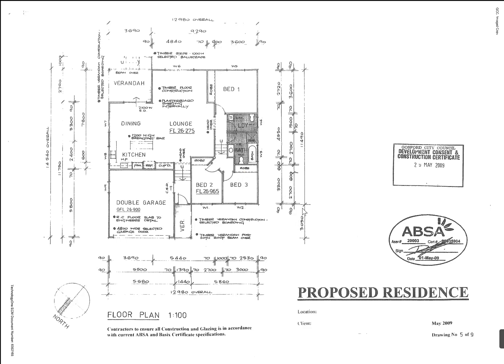Now, looking at the dimensions, basically what happens with all projects is that the furthest dimensions from the actual building give us the overall length and the width of the building, and that's what we've got here, across the top of the drawing and the bottom of the drawing. It's always good that they both match up. Believe it or not, I worked on a big commercial job years ago where it took the architects ages and ages to get the dimensions to close around the outside of this office tower. That was before the days of CAD drawing. We've got 12,980 overall width, and then up the left hand side 14,540 overall distance there.